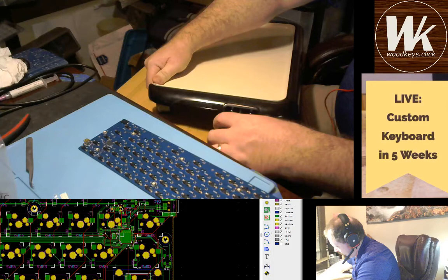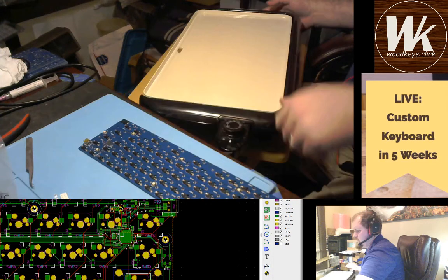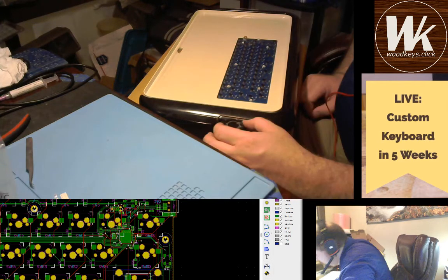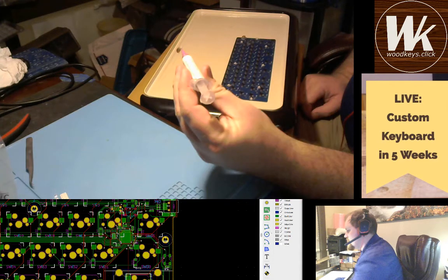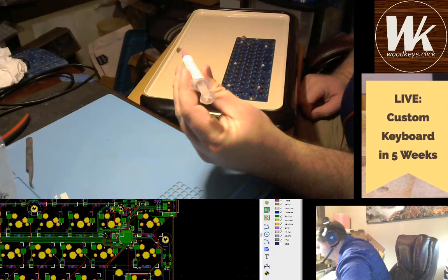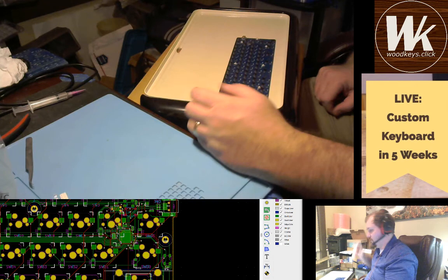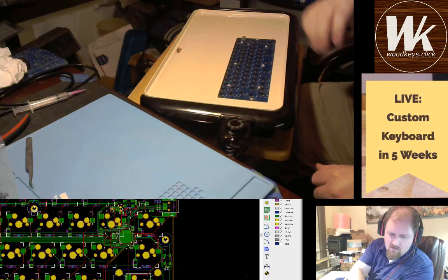Now a lot of people will modify these to do the controlled temperature, the appropriate heat up curves and all that stuff, but I've kind of found that this solder paste melts at 278 degrees Fahrenheit. So I set this thing in here between 275 and 325. Let it heat up, kind of keep an eye on it. Seems to work pretty good.